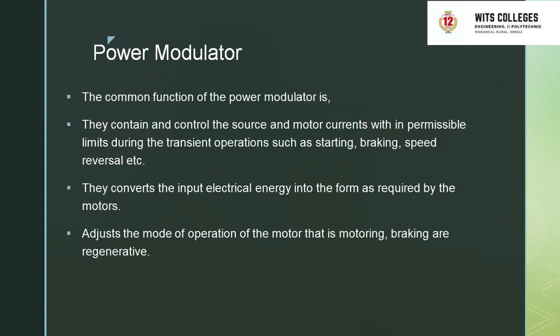Next, coming to power modulator, as I said, power modulator will perform a number of functions. First of all, it will control the source and motor current within the permissible limits during the transition operations. Next, it will act as a converter, and next it will adjust the motor operation, either motoring, braking or regenerating.